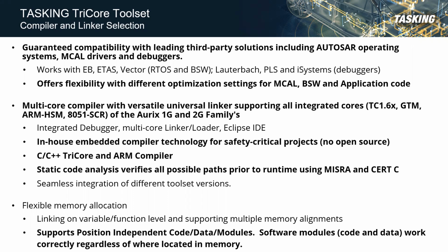And last but not least, our newest version of the compiler supports position-independent code and data modules, where they will work anywhere within the memory space. And this is very beneficial, again, for things like software over the air, where a new feature, say, is developed late in a development cycle, or after a vehicle is already in production, and now we're trying to dump that into Flash via software over the air update.